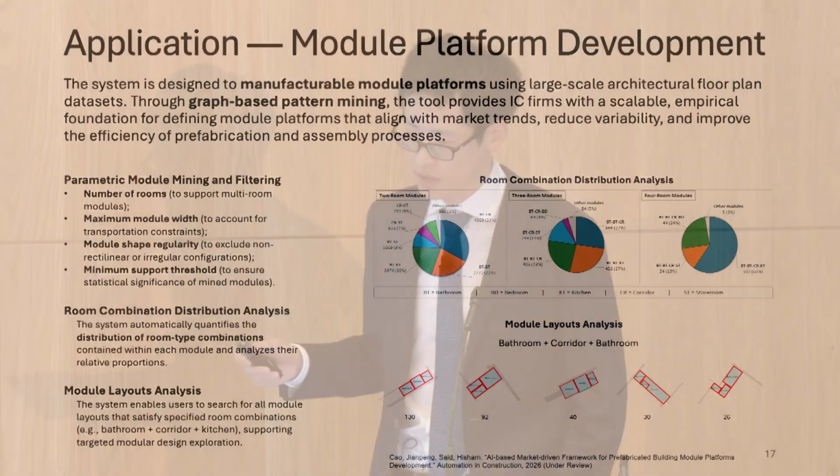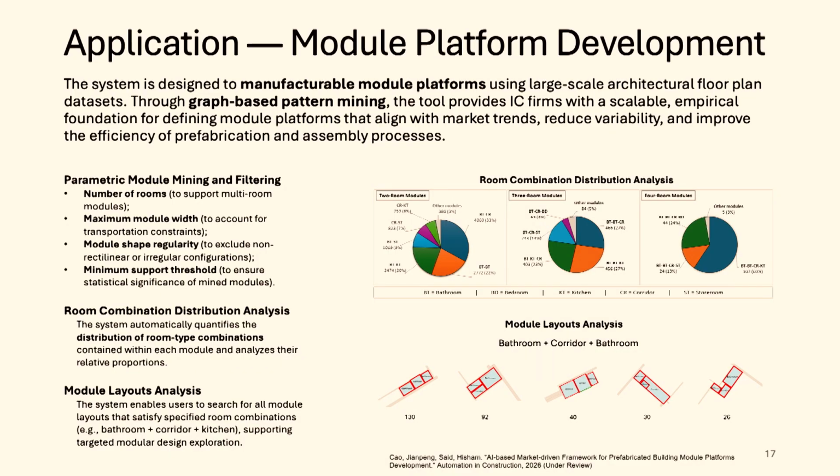This application is for modular developers or designers. What we propose is a data-driven framework to help you identify the most representative module platform that matches the local market demand. How we do this is we collect a set of data that represents local multifamily residential housing projects. We use pattern mining algorithms to identify the most frequent module patterns among the historical data sets, and we define the number of recurrences of a module in the historical data as support.